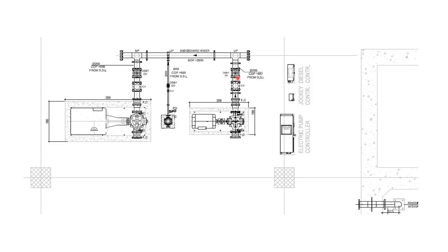Please note, if the discharge side of the fire pump size is less, then we need to have a concentric increaser, and on the suction side, if the pipe size does not match with the suction side of the fire pump, we need to add an eccentric reducer.